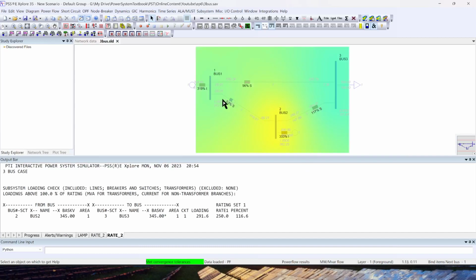And you can see it generates this nice visual voltage contour. What this basically means is green is where voltages are close to 1, yellow is above or greater than 1. In most cases, when it's red, it's closer to its upper limit or beyond. So this is sometimes useful to quickly locate the areas or zones where you may have voltage issues. And that's where this could be very powerful visually to identify those.